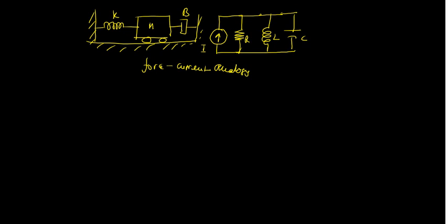So now please see here what is common with all. Let's say that a voltage is common with all. You see, this point is same, so voltage is common with all. So can we say that this is the input current, and the current which is going to flow here is IR, the current here is IL, and the current here is IC. Remember, in the previous case we applied Kirchhoff's voltage law. Now what are we going to apply? Kirchhoff's current law.